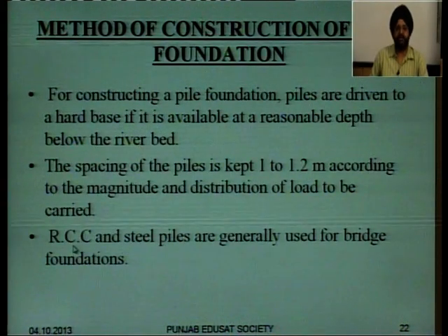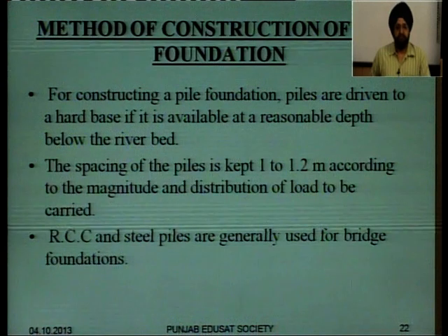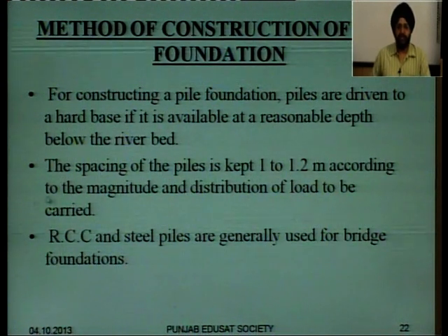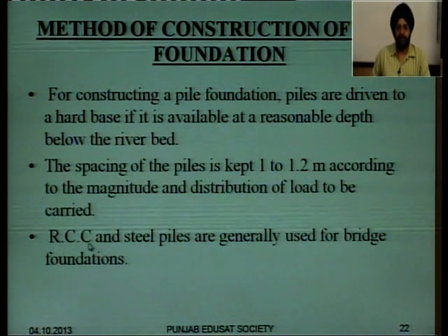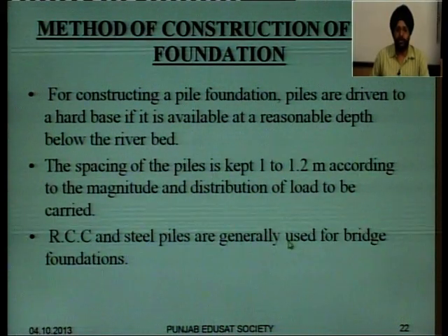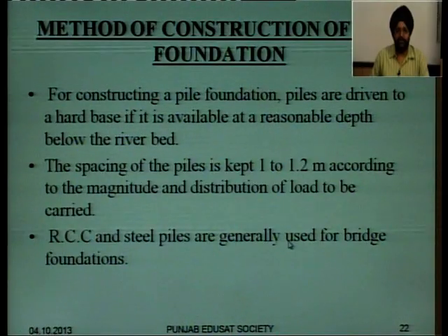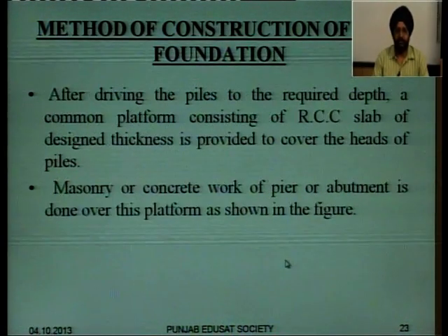Something more regarding its materials, piles can be of RCC or steel piles, these are very common. It may be timber piles also. RCC and steel piles are generally used for the bridge foundations. So, this is regarding the method of construction of pile foundation.